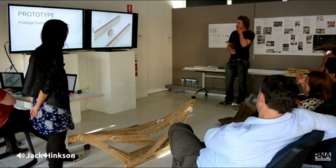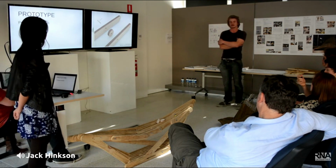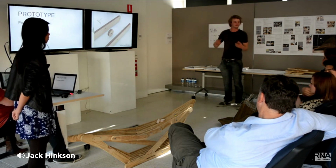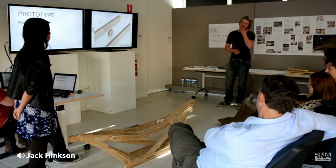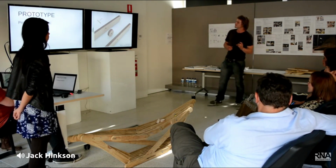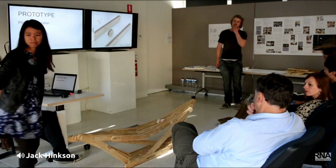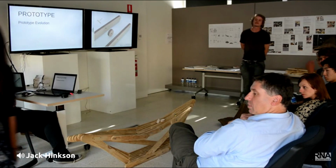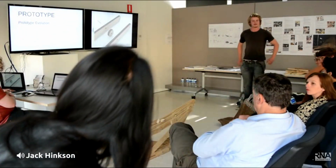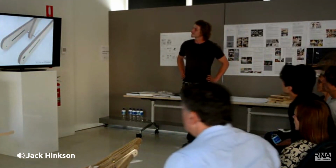Now the dowel joints, we came to the conclusion that they were inappropriate for the final construction because we're trying to produce at a fast rate. The dowel joints required clamping and time for the glue to set. And as you'll see on this prototype, it came apart in a few areas as a result of us moving around in the process of assembly. And then for our little slider joints there.